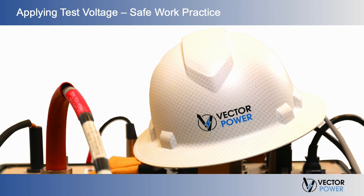Before making insulation test connections, the circuit under test must be switched off, de-energized, isolated, and checked to ensure safety. The circuit must not be re-energized while the instrument is connected. Circuit connections must not be touched during an insulation test. After completing a test, capacitive circuits must be fully discharged before disconnecting the test leads. Capacitive charges can be lethal.